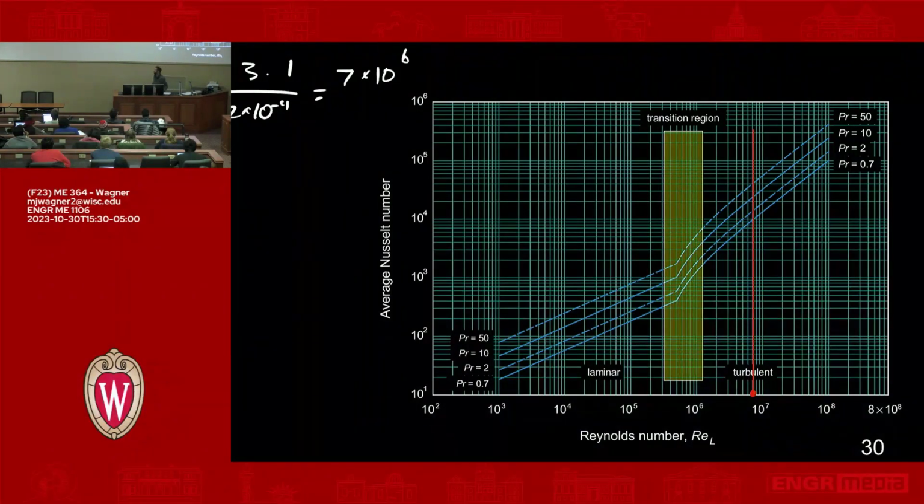The other piece of information I have is a Prandtl number. The Prandtl number was 2.61, something like that? 2.69, 2.7. So these multiple curves that show up, these blue lines, it's a little hard to see, these all correspond to different Prandtl numbers. This solution has been plotted out for each of these Prandtl numbers. There is one for 2, that's pretty close. So I'll maybe pick a number that's slightly above that 2, and closer to the 10, maybe it's right here.